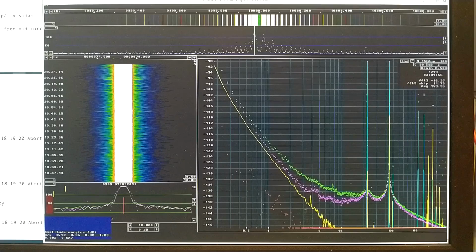And the reason was that the receiving copy of Linrad would send messages back, using the same thread as was used for receive. And that blocked receive for a couple of milliseconds too much. So there is no reason to send any information back when doing sideband noise measurements. So now I'm running at 96 kilohertz, and then I don't have to do any calibration because the sound card is flat enough. But I have done some other experiment before I start to modify the oscillator.